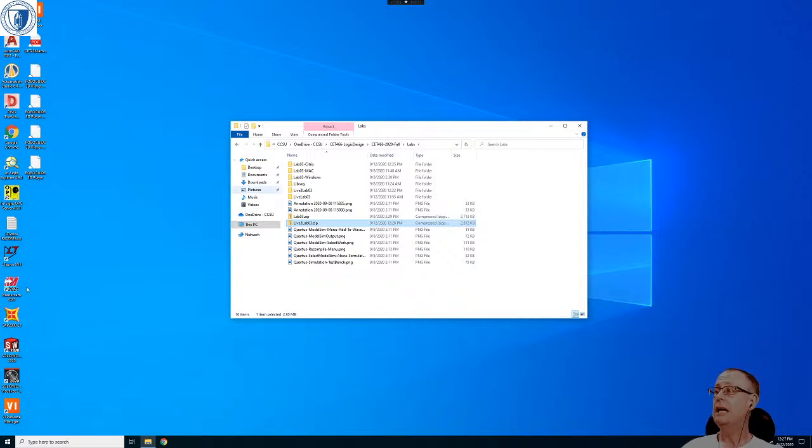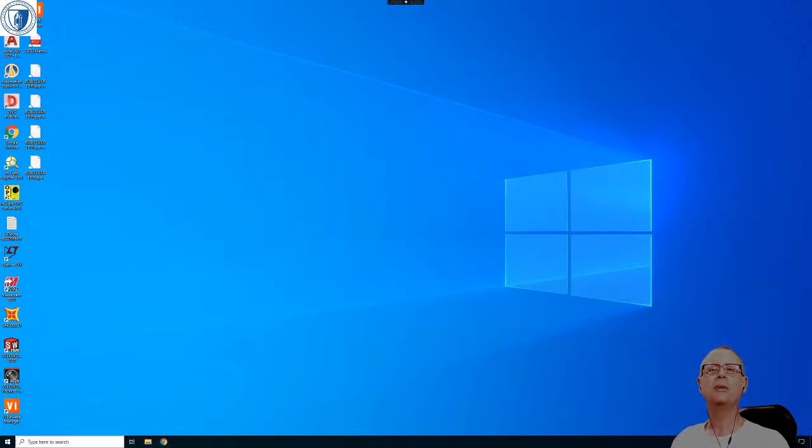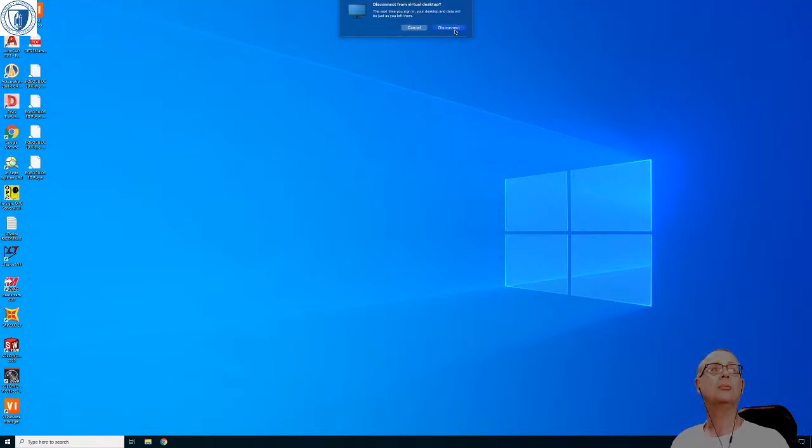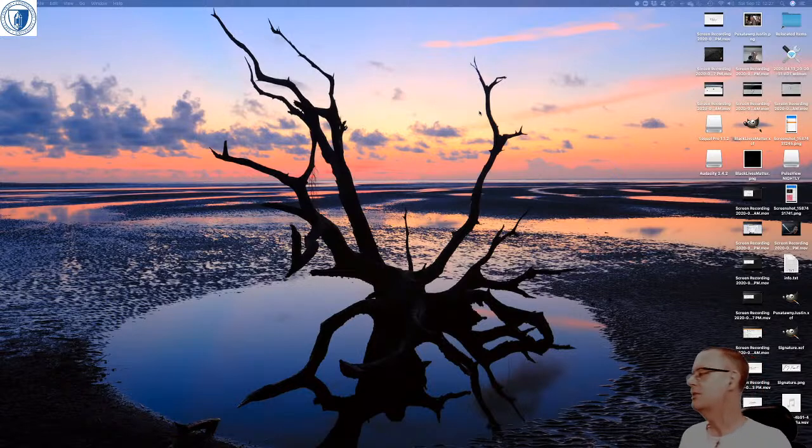Okay, I think I'm done, unless anybody has any other questions. I killed Quartus there, so remember you won't be able to zip the file unless you're out of Quartus, because it complains about something getting access to the file when it tries to zip it otherwise. Upload the VHD file and a screenshot of the successful compilation of the VHD file, Jacob. Okay. Let me do that right now.